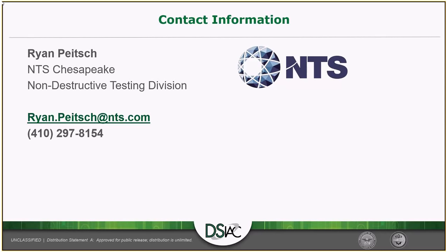That's a great question. So the CT scan data goes directly from the scan data. We can go right to an STL or a point cloud. That's the direct export we can do. And the automation of that is 100% dependent on your scan quality. The longer you scan something, and the different types of materials that are in there, all influence this. But say you have a plastic component that's 100% plastic, if you do a nice 1-hour CT scan on that, you can get an auto threshold and save out to an STL in less than an hour. And then it's completely automated.